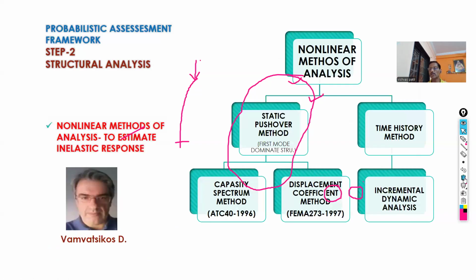So this is about the definition of the nonlinearity and how to assign the nonlinearity. After assigning the nonlinearity, perform the nonlinear analysis. Why perform nonlinear analysis? By performing nonlinear analysis only, we can calculate the inelastic response of the structure and the failure mechanism in the structure. Therefore, we have to perform the nonlinear analysis.